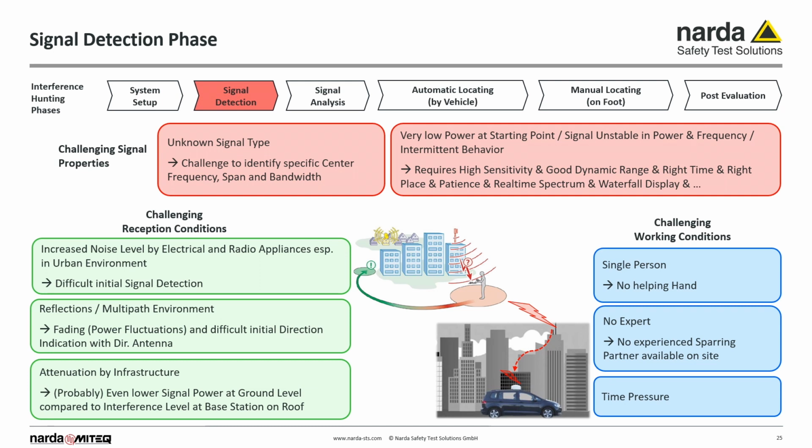Moreover, when taking measurements close to other radio transmitters, especially when they are intense like a base station, the risk of overdriving the measurement device increases severely. Overdriving a spectrum analyzer will lead to harmonics and spurious, which forbid reliable measurements.